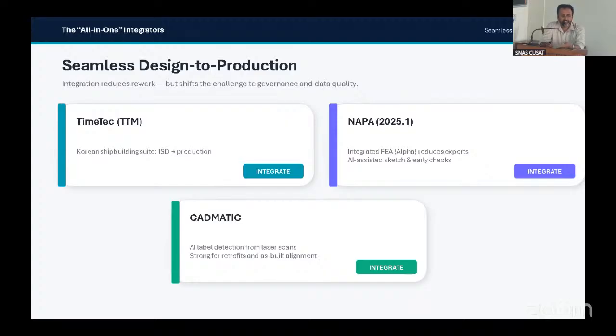So in this particular case, what happened was that the production approved a thicker bracket, but finally when it went for reiteration, we found that that particular thick bracket with a hard toe was creating a hotspot over there. So then again, it's a fatigue problem. From a fatigue perspective, they wanted to reduce the thickness of the bracket back to whatever they wanted, but then the production had already taken the liberty of taking whatever buffer they had and got it approved. So that's where the integrated approach comes in.